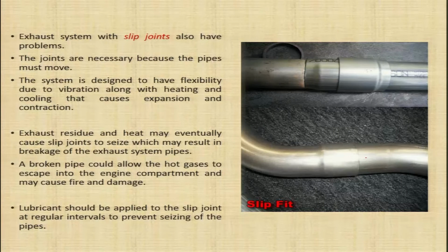So, flexibility is required. In case these slip joints freeze and there is no movement, this will result in cracks in the exhaust pipes. Exhaust residue and heat may eventually cause slip joints to seize, which may result in breakage of the exhaust system pipes.